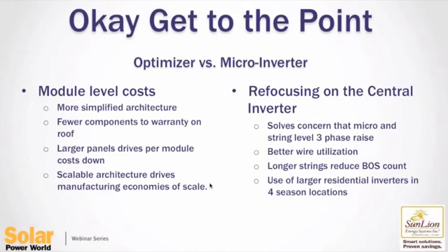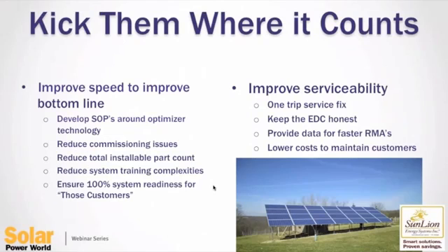And what we've seen is that allows us to turn on some of the larger residential inverters from, say, SMA. We have a very tight MPPT window. So by the time we were able to turn it on, we were overvolting before. Now we're able to get these things on, which has allowed us to remove some more costs by using a larger inverter that has some cost savings built into it.